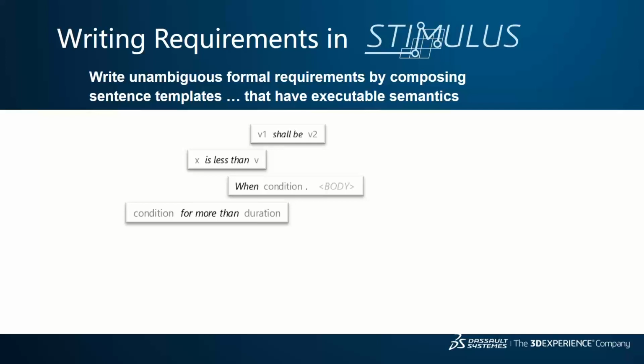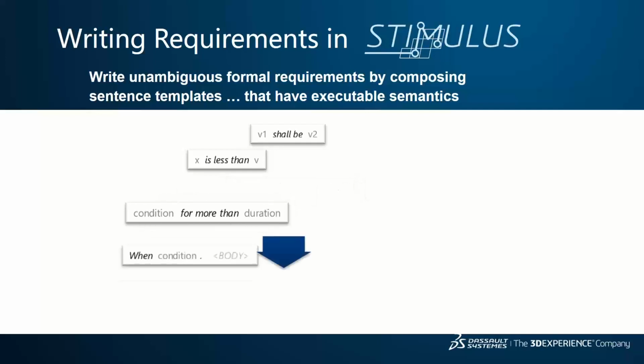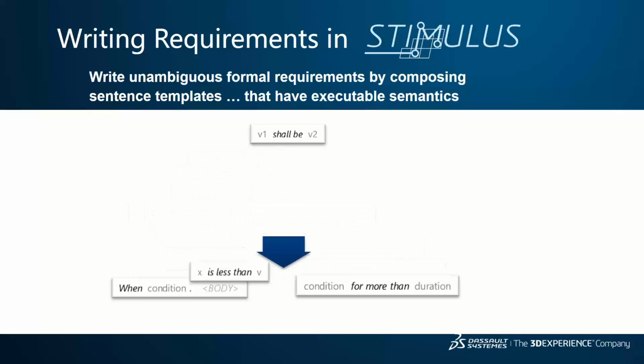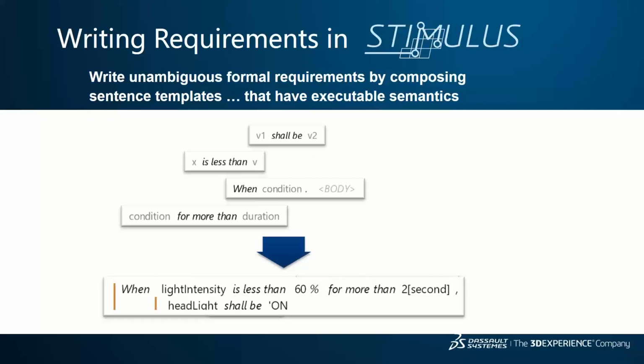I mentioned that you create the requirements based on templates. Stimulus comes with a language, which is actually customizable and extendable, and you combine, as I will show you in the tools very soon, the templates to create the sentence you like, and then click on the play button and simulate, and look how the system behaves according to this requirement. It's as simple as that.